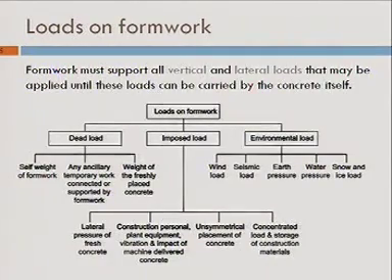Under dead load, you have again three categories: self weight of formwork, any ancillary temporary work connected or supported by formwork. Then you have weight of the freshly placed concrete. So these are some of the major dead load categories. Likewise, we will see imposed load also.